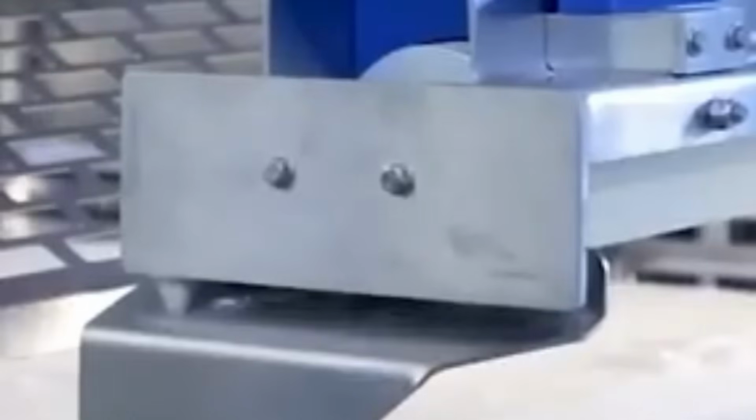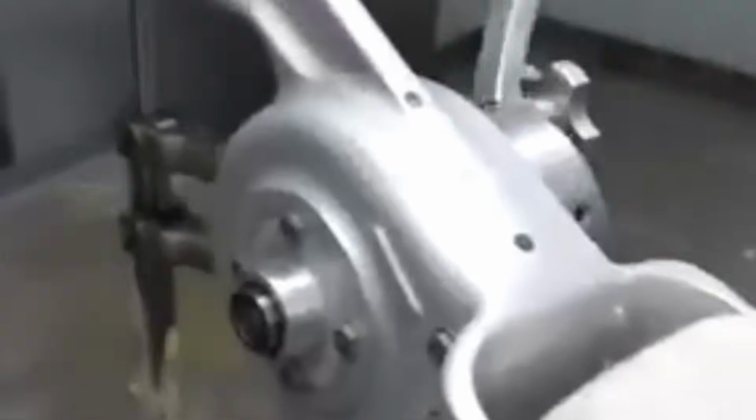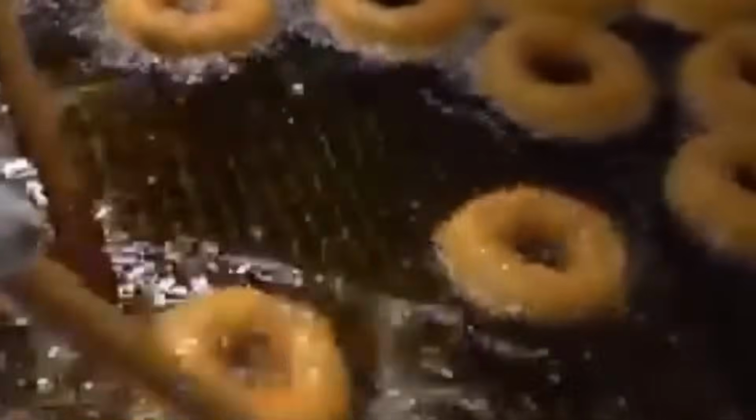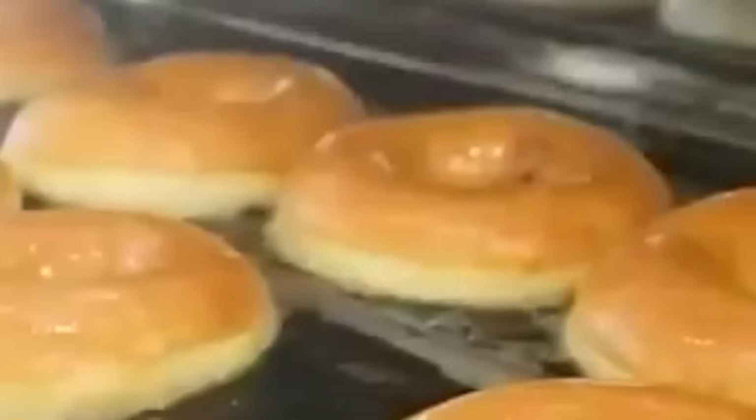Filled donuts follow a different path. These start as solid discs cut from sheeted dough and proof separately. After frying and cooling, each unit is aligned on a conveyor with a multi-nozzle injection machine. The filling system uses positive displacement pumps to inject jelly, custard, or cream into each donut at a fixed volume. Nozzles penetrate the side and retract automatically after filling.